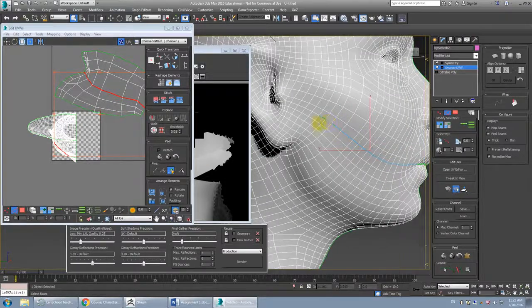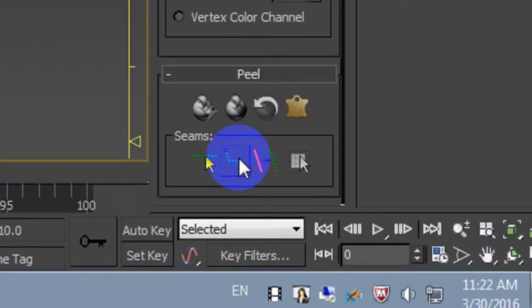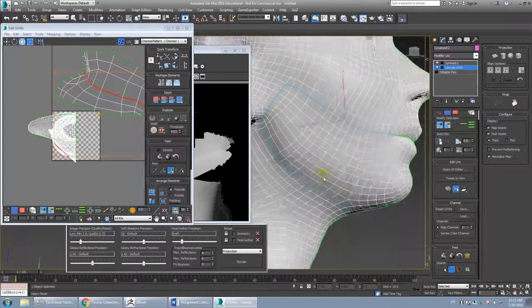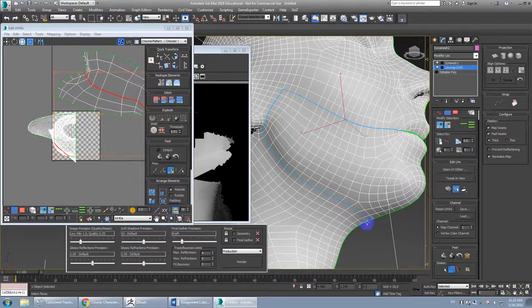So you'll see that'll turn blue. And then if I wanted to, I could also go F5 again. Yeah, F5. I'll go point-to-point seams. So what that allows me to do is just click on a vertex and go vertex to vertex, and you see it'll kind of create this isolated seam here. So I can quickly get the jaw selected.